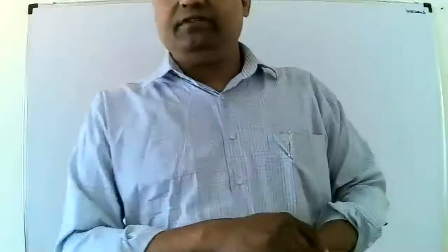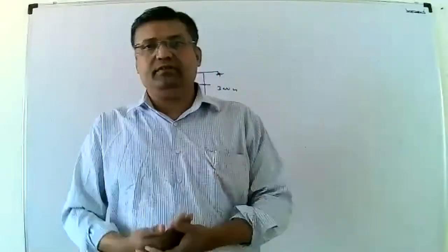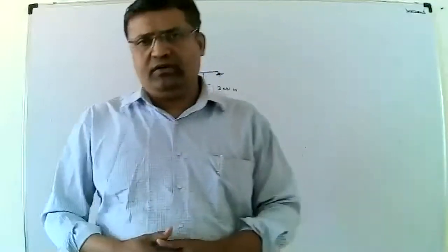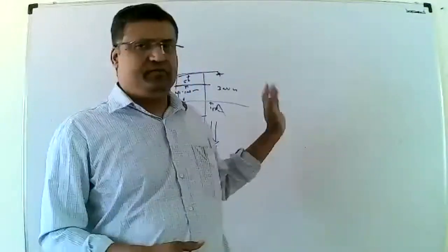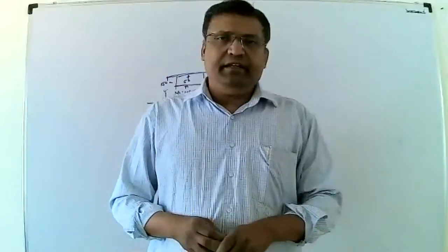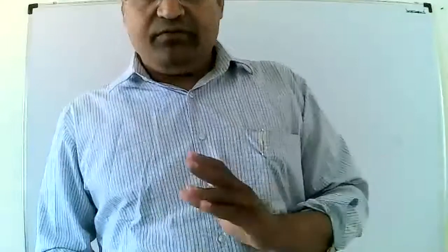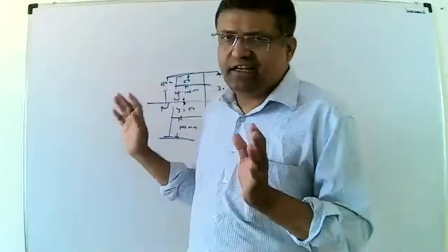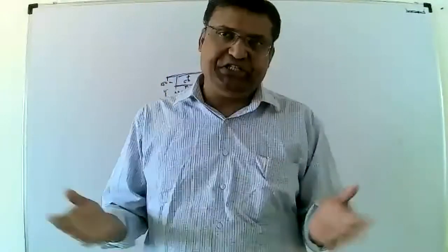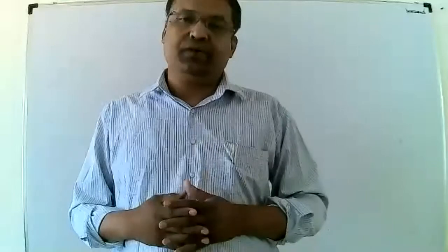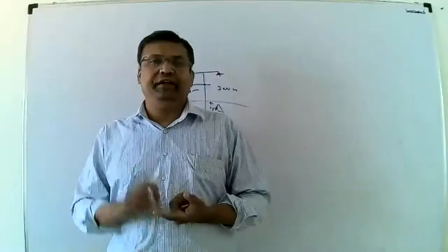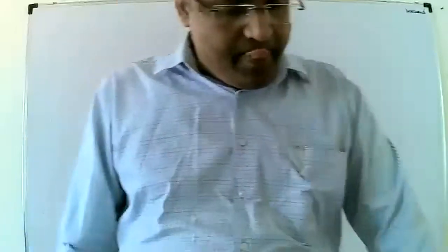In the middle, the shear stress is maximum. In any rectangular section, the stress distribution diagram will be the same. So you can easily solve such examples. We calculate shear stress at any distance with respect to the neutral axis, and you can easily draw the stress distribution diagram.